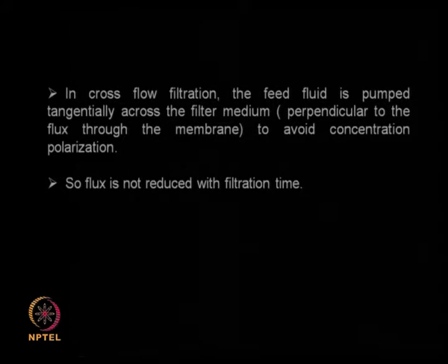In a cross flow filtration, the feed is pumped tangentially across the membrane surface, that means instead of perpendicular it is almost flowing parallel. That way you are preventing the formation of the boundary layer, you are also preventing the formation of the concentration polarization. So the advantage will be flux will not get reduced with filtration. So that is the main advantage when you do a cross flow filtration.